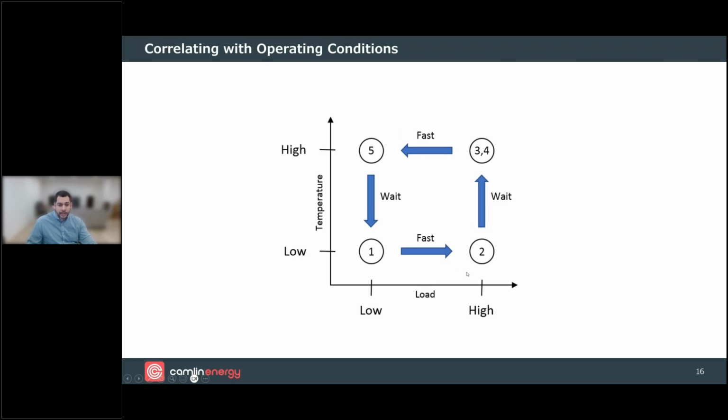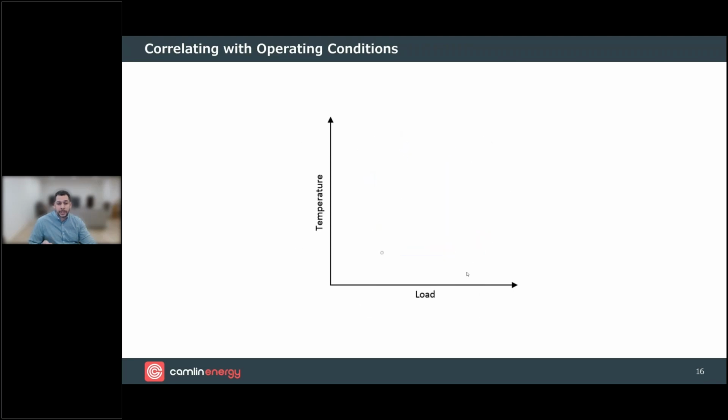The rationale for that is, of course, based on the table and the failure modes we talked about previously: different defect types will reveal themselves at different operating conditions. Our online monitoring passively monitors the information continuously at different load and temperature points. It would be very impractical to require this sort of measurement at different operating points, with load changes and waiting for temperature stabilization, in a field installation, because O&M costs would be very large.